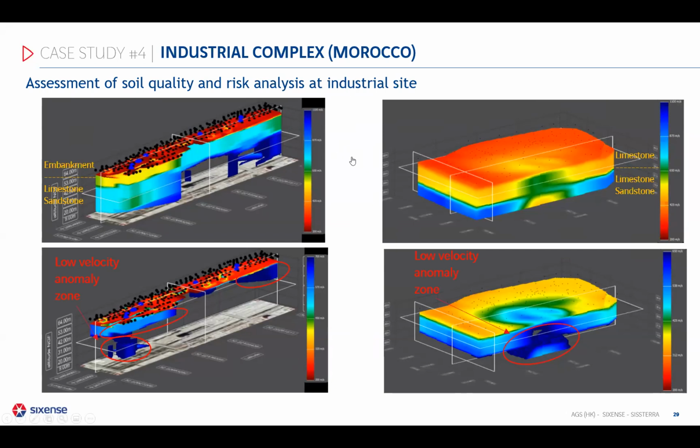And what we were looking for was, again, these anomalies of the velocity that we could observe in these homogeneous seismic horizons of shear velocity. So we did have general information about the geological structure as the identification of the different seismic horizons, but we were also focusing on these anomalies that we can observe here that might be related to the presence of cavities. But again, they might be, but we cannot be sure that these are cavities. What we can say is that we can observe low velocity anomalies. They might be related to presence of cavities, or maybe the presence of altered material.